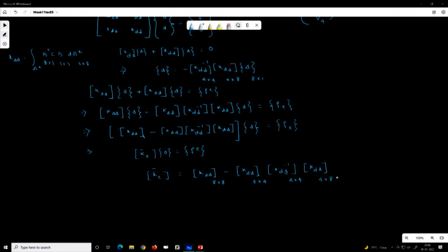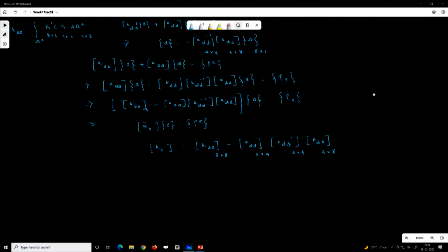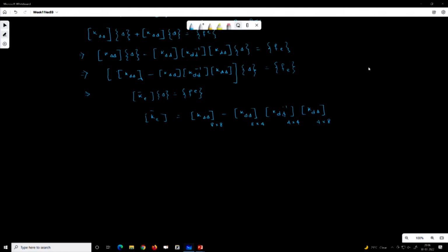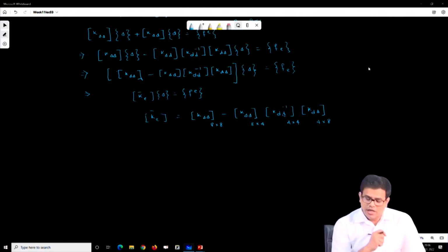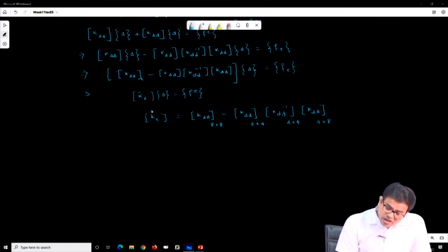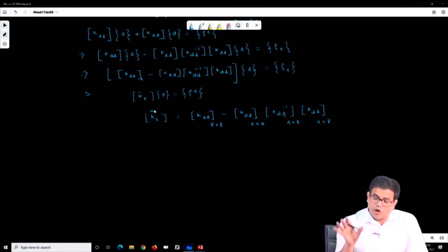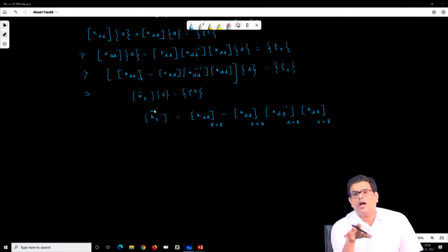Now if you use this, then you can actually represent the bending modes correctly. Even with one element through the thickness, you can correctly simulate the bending problem. Now there is a problem in this element. It was soon discovered that it doesn't pass the standard patch test.